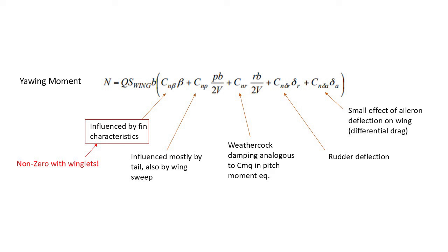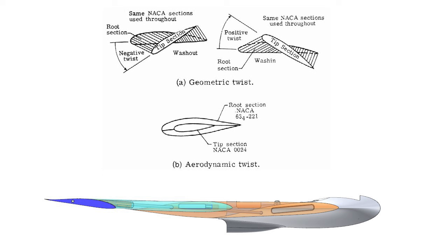Talking about increasing directional stability now, remember from the last couple of videos, we can achieve sufficient directional stability through a combination of sweep, taper, and nonlinear twist in a flying wing, but even then the stability can still be low and challenging. Winglets here can provide a healthy increase to the stability and can also provide some slight efficiency increases, if any. Moving on to practical design, how should we approach the design of a winglet?